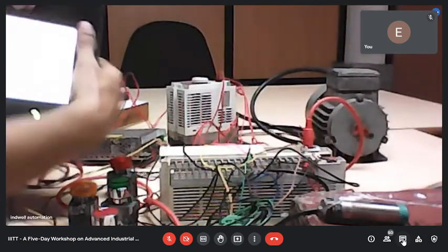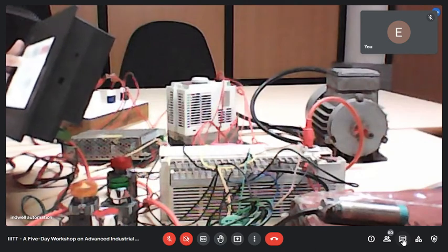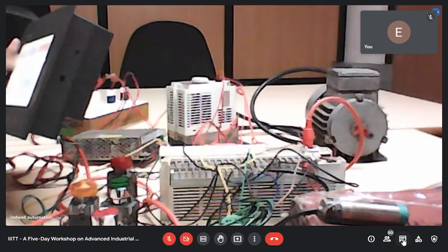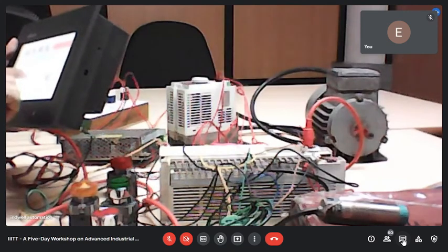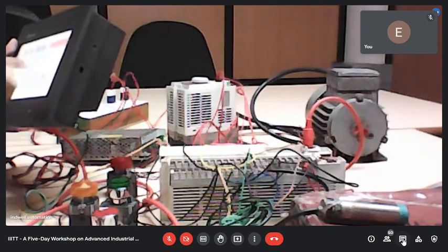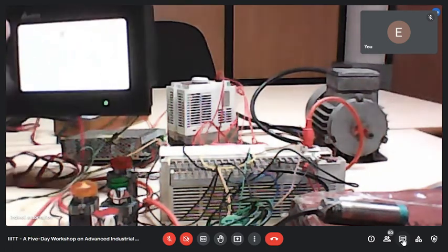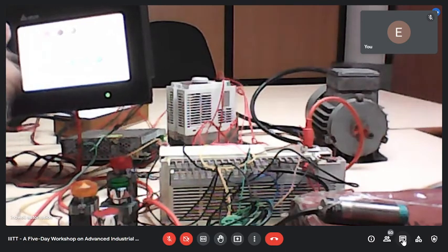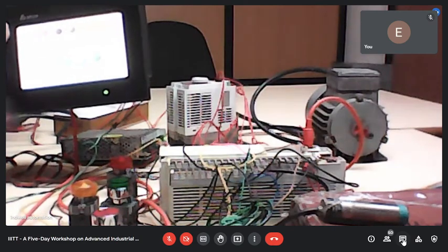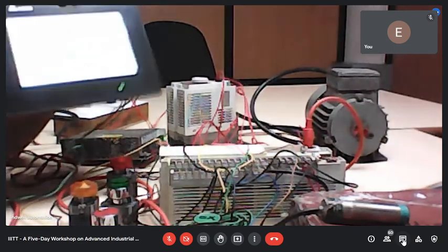Okay, so very first I need to enter values. For that, I just click preset value number 1. As I click, a numpad has come. On that numpad, I can enter, okay, first it should be 5 seconds. Second timer, now 4 seconds I'm making. Third timer, I want to make 6 seconds and next 7 seconds. Enter. So by touch only, as you touch that preset value in the HMI, the numpad will come and you can enter the number you want. After that, first I shall operate it from the push button, and then I shall operate it from, there is no option, you see.